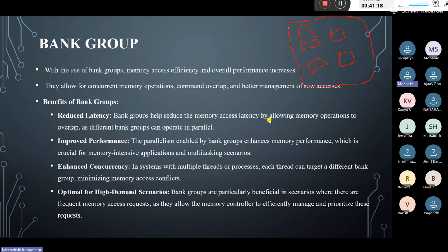This means in DDR3 we don't have the bank group concept. Here, for example, rows 0 to 15, we are selecting one row, the seventh row. After selecting it, the data present in the seventh row should be shared into this buffer. After the seventh is stored, we don't want to select yet, because I need the ninth also.